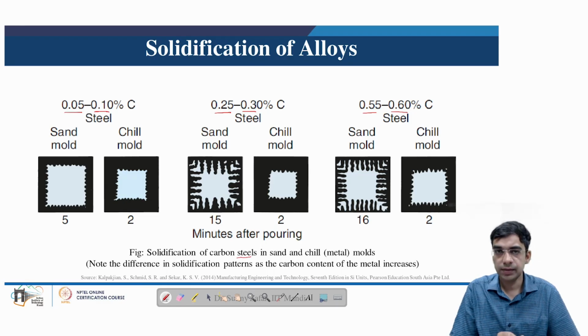So that is why it is very important to understand how various alloys solidify and what the role of solidification rate is on the end microstructure, because in the end it is the microstructure and the compositional differences which decide the property of that particular material.